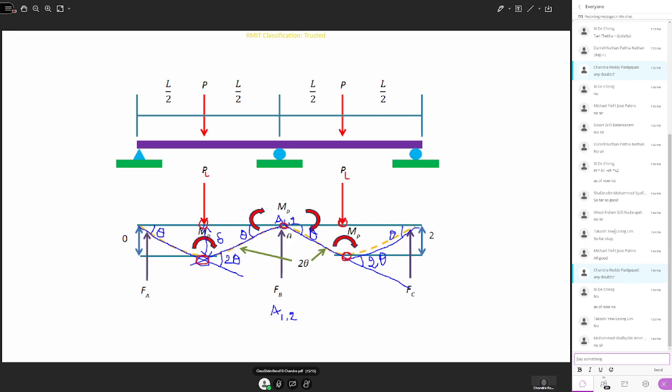Elastic stress strain relationship is straightforward, but when the material enters into plastic deformation, you need to understand the plastic flow rules and the yield stress calculations. Followed by the plastic bending, how you can establish the neutral axis, then how you can calculate the plastic moments and elastic moments and the residual stresses. Then the last part is the plastic design, where you calculate the plastic load when the plastic hinges are developed on the structure.